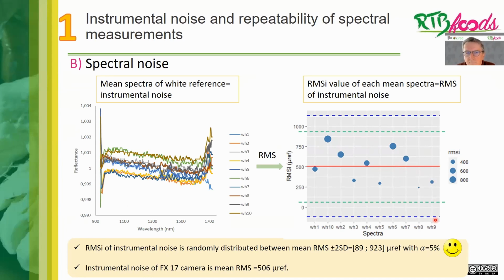When you work on a sample, we are not looking to do a lot of spectra from the same sample. So we need to define the optimum number of spectra for one sample. To have an optimal number of spectra, you first need to know the repeatability of the measurement, and second, know the variability of your product to be able to catch the entire property of your product. So that's what we have done in this little experiment, just to highlight how to do it. It's a procedure to start with a new product, to know how many measurements you have to do for your product.